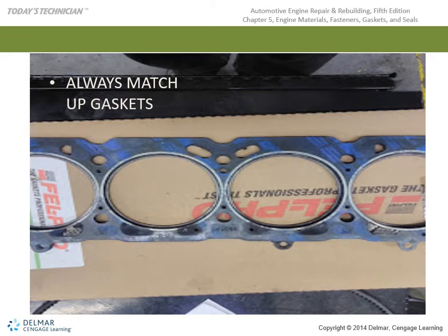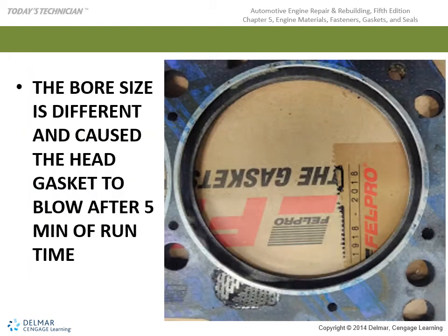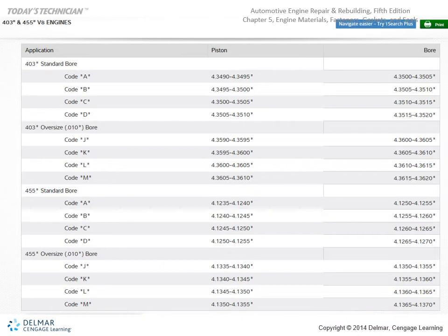That's what comes out of this. We lay them over each other and inspect the hole spacing and sizes, and you got some dowel pins and a variety of exact formations for your fire ring and your materials. If you have the wrong gasket, it could be the end of that engine. So you want to be very sure that you have the correct gaskets, especially for cylinder heads.